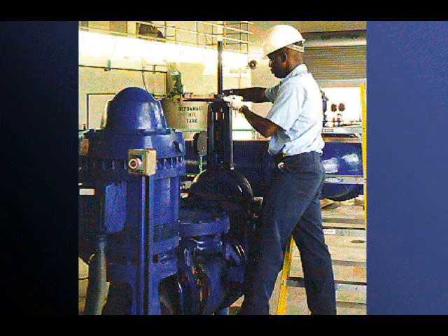Throttling the discharge valve reduces the demand for increased current during startup. Throttling of the discharge valve should occur only for a short time during starting of the pump, as extended throttling can cause excessive wear of valve parts. This strategy is sometimes used on large pump motors and is usually a part of the automated startup sequence.